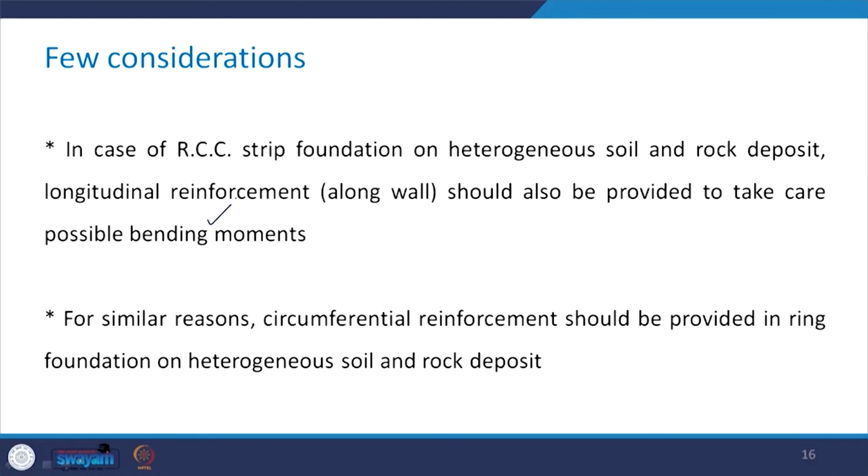So, when I say heterogeneous soil and rock deposit, what that means is that below the base of the foundation, in some part you have the occurrence of soil and some part of the foundation is lying on the rock deposit. So, in such cases, because the strength and the deformability characteristics of soil and the rock deposit are altogether different, we need to be extra careful.